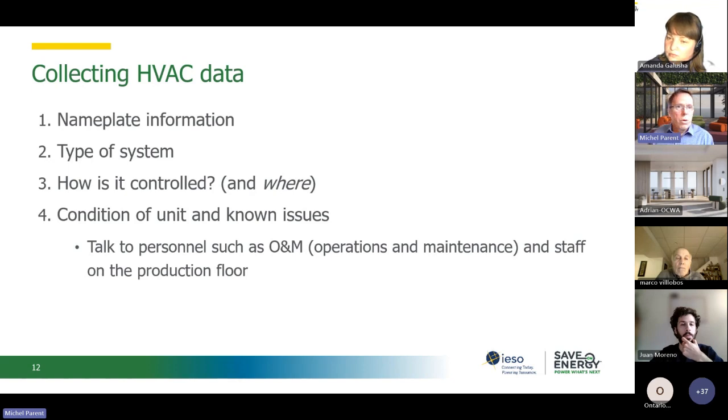Good example, you collect information about an air handling unit, and you talk to the staff and they tell you, well, that system has never worked over the last 5 years. So if you were planning to upgrade that and think you're going to get energy savings compared to your current condition, that obviously would not happen. Obviously, you will get savings compared to if the system was running and you're replacing with a better system, but you need to know what are the current operating conditions, as well as any maintenance issues with a system.